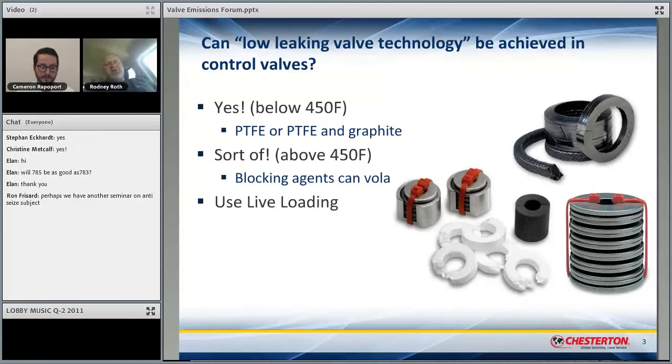So there's a lot of issues with OGI on the lower end of the leakage levels, and they have their place, but they're better to pick up, just point at one unit and say, okay, this unit's exceeding their limit, let's go find out why. But you can't point it at one valve and say that's 105 ppm. It can't be done. Yeah. I know that more people are trying to get into quantitative OGI now, as opposed to qualitative, but it's a very new technology, and it'll probably be a while till it can, or if it can ever really, replace something like Method 21 monitoring.